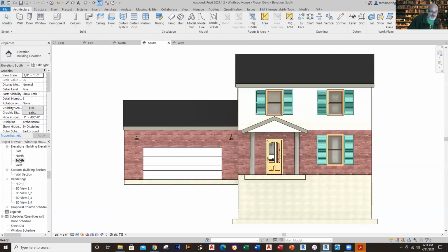As we get into this, we're going to look at the south view. Now take a look at the south view. If you take a look at the porch right here, you can see that the porch is 1 foot down, and then you actually have where you're stepped up here. That's where level 1 is. Down here is where your foundation is, and grade is where your garage starts. That's typical procedure. Your grade is typically what you drive into in your garage. So you've got different levels for the garage and the first floor. That's one thing you want to be aware of.